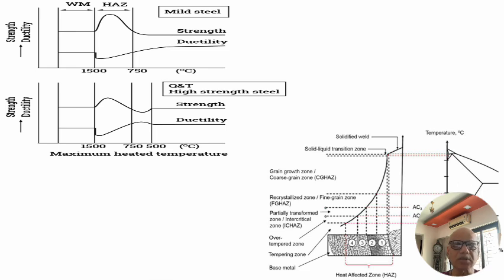come down drastically different in the heat affected zone because of the various heat treatments which this zone is going to undergo, from the melting point to room temperature. Each of these zones will give different grain size and different grain orientation, and this makes the properties vary even though the chemical composition is not going to change. And as we go to high strength alloys, you will see sometimes the strength reduction, especially see this point